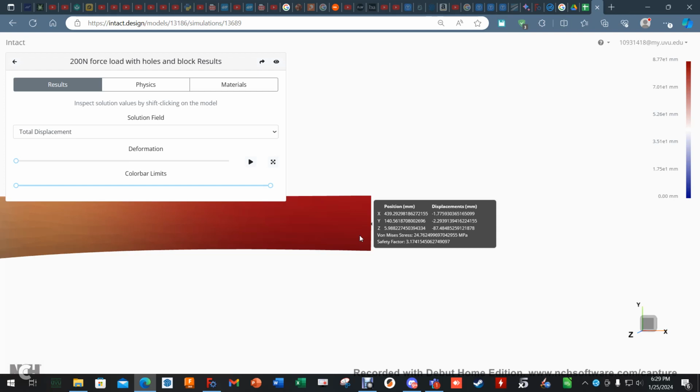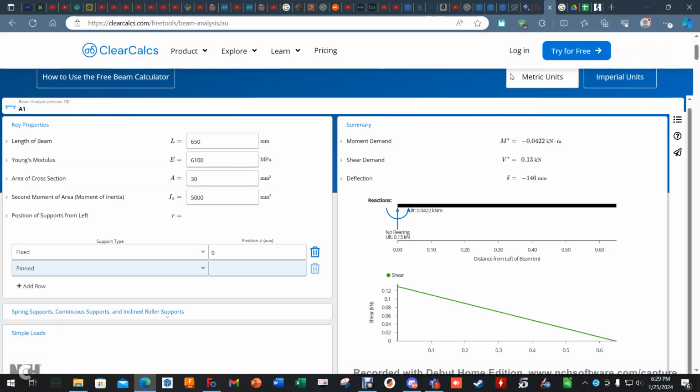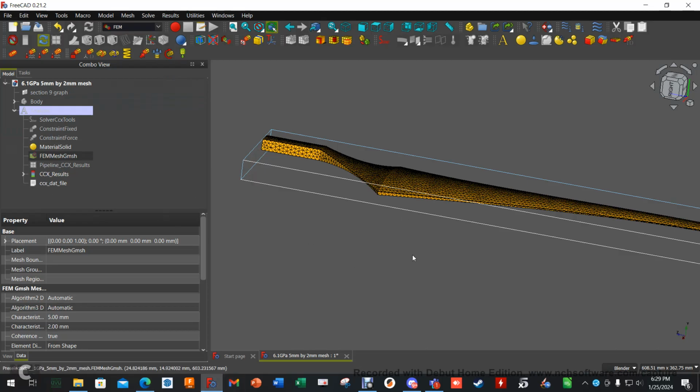So we're anywhere between 90 to 146. Now, I wouldn't really trust this 146. I mean, you can, but remember, this is just based off of a simple beam versus my geometry, which is a little different. That's why I had to make sure these are as accurate as possible. So that's why I say I'm in between the two, which means I'm probably pretty dang close. Now, you could add up all three and take an average, which would be fine. But I'd probably trust this result just fine.